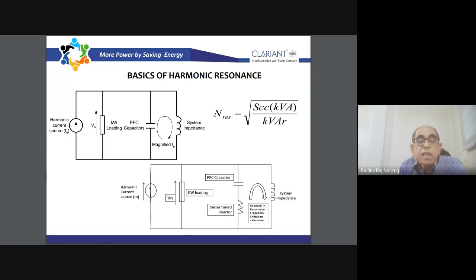What we do is, capacitors are not connected as a plain capacitor. They are connected along with a reactor in series. And this reactor is, normally we have 7% reactor. 7% means suppose 100 kVR is the capacitor, the reactor is 7 kVR. So what it does is, it is doing 3-4 jobs. One is that when the reactor is there, it is limiting the current.